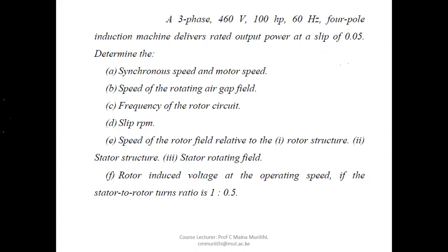What will be the speed of the rotating air gap field? We have already discussed that the air gap field is the one which rotates at synchronous speed. What will be the frequency on the rotor circuit? Now, when you look at the rotor and the stator field, you should look at it as two cars moving in the same direction, but one car is slightly faster than the other.